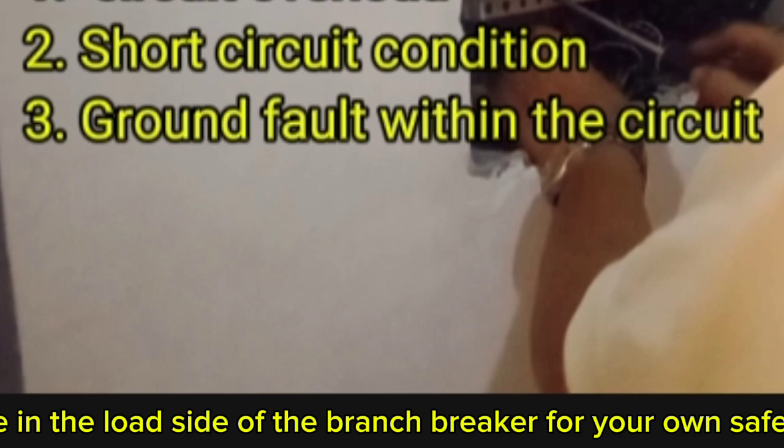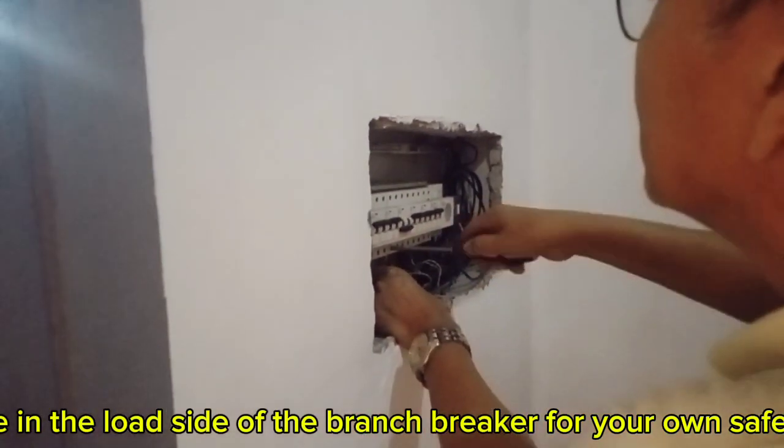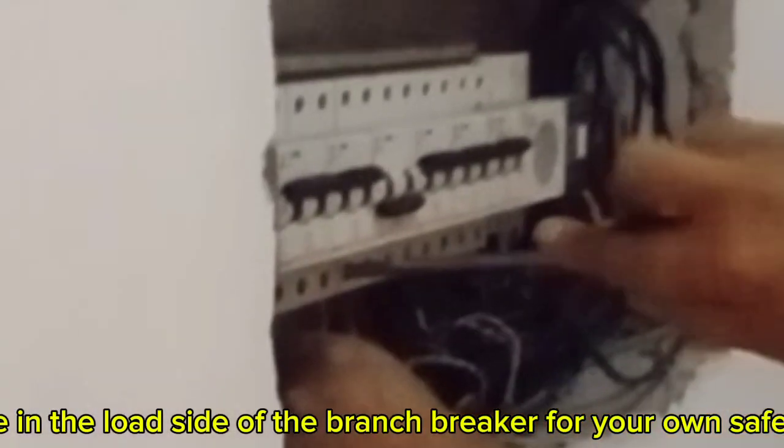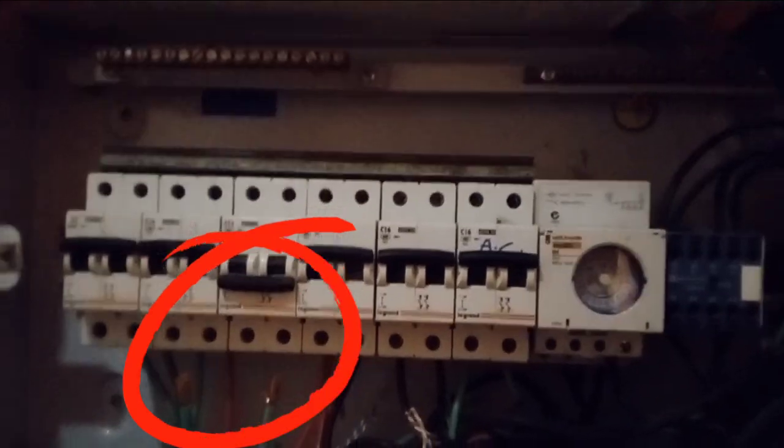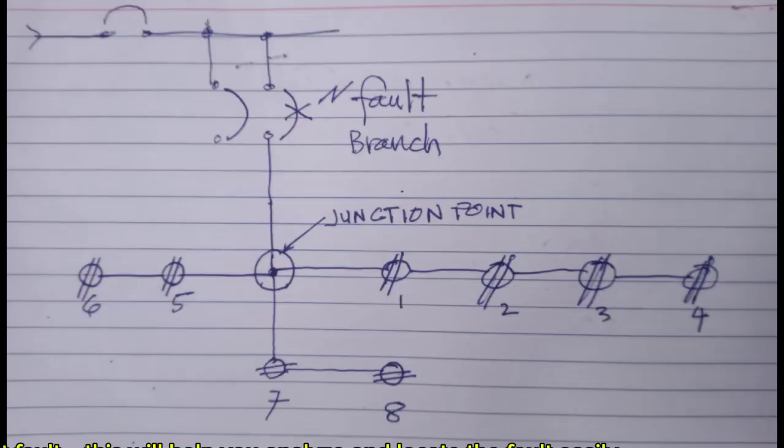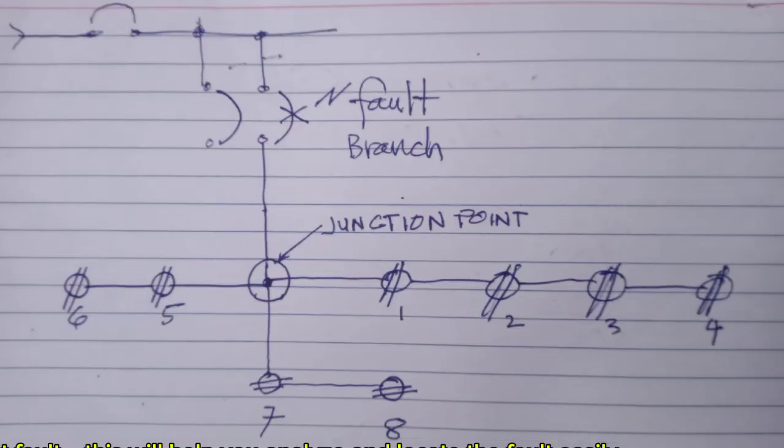The third step is to disconnect the line in the load side of the branch breaker for your own safety and protection. Always be careful not to make your bare hand in contact with adjacent live wires while working with an energized panel. Make a one-line diagram of the circuit at fault. This will help you analyze and locate the fault easily.